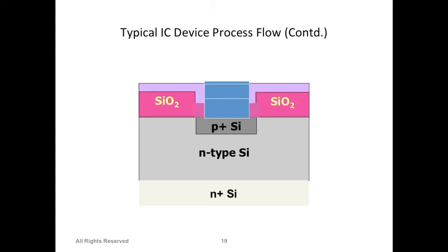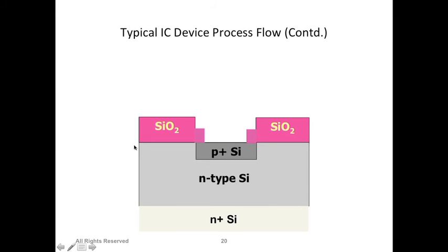And then that is the opening. Now we can remove the photoresist from there. Now this pattern is transferred inside the silicon dioxide, and then I just remove the photoresist, okay, to make it more clear. Now let's say if we want to deposit aluminum, what process can you use now for aluminum deposition?